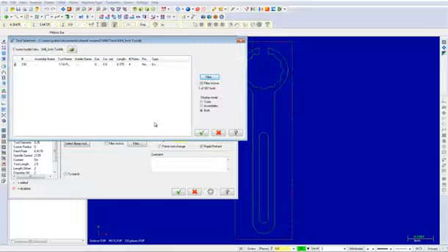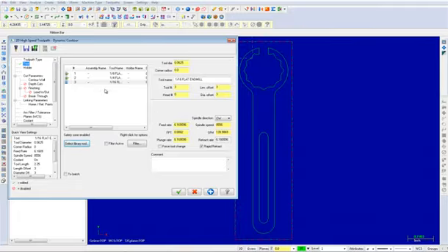In the Tool Selection dialog box, you should now only see a 1/16 inch flat end mill. Select this tool and then choose the OK button. Your tool will appear as shown. Input the following comment as shown. Once complete, select the cut parameters.